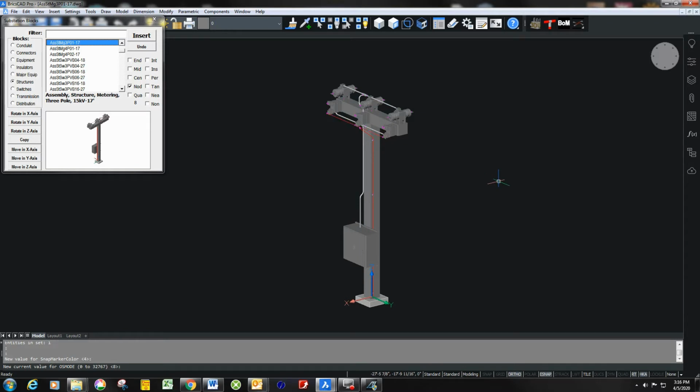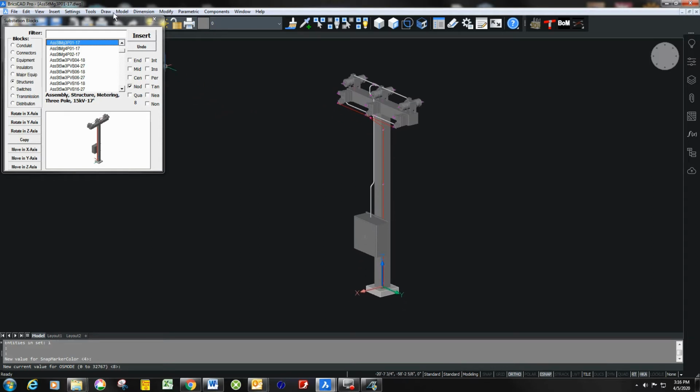Now if you try to nest an assembly within an assembly, then all of the blocks that are in the other assembly, which would then be nested 3 deep, would not be found. So if you find it necessary to do that, then if you insert that assembly, you would need to explode it so that they would be individual blocks and assemblies.